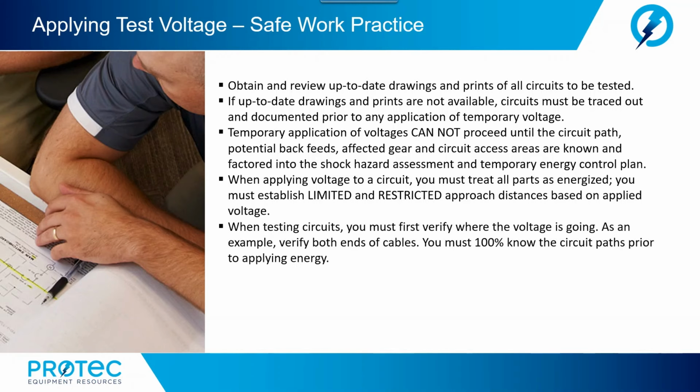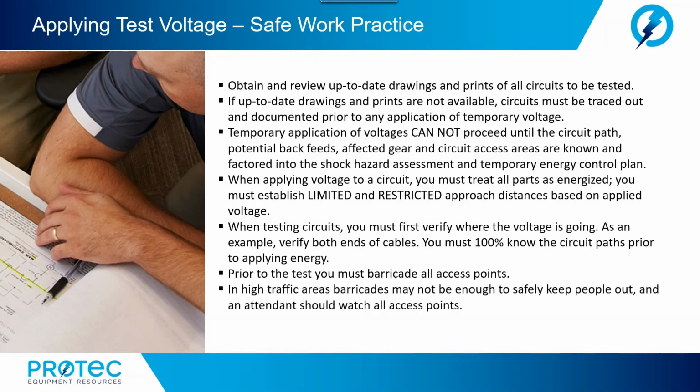When testing circuits, you must first verify where the voltage is going. As an example, verify both ends of a cable or a long busway system. You must 100% know the circuit paths prior to applying energy. Prior to the test, you must barricade all access points. In high traffic areas, barricades may not be sufficient to keep people out, and an attendant should watch all access points.